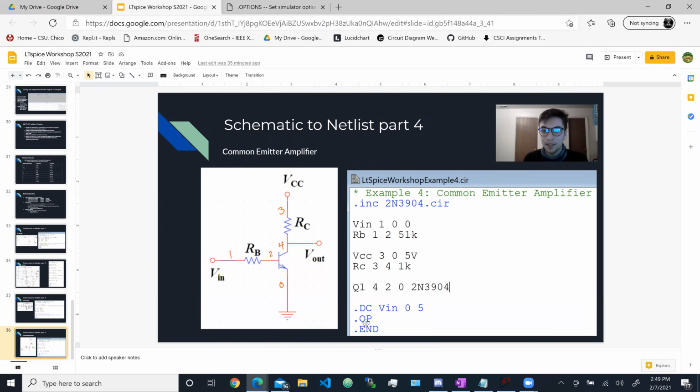The reason I wanted to go over this example is because instead of the .ac sweep, this is a .dc sweep. And this is nice so that we can do characteristic function or characteristic graphs, tables, or whatever.